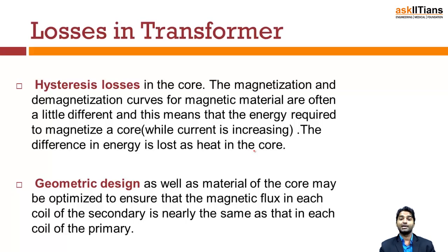We already discussed that magnetic lines of force pass through the secondary coil, but it doesn't mean the core demagnetizes 100%. Some residual magnetism is also observed that causes hysteresis loss, covering retentivity and coercivity in this concept.